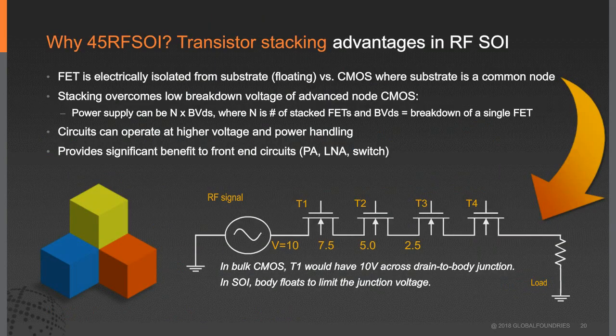Why 45 RF SOI? This is the SOI technology where the FET is electrically isolated from the substrate. So it's floating, versus CMOS where the substrate is common mode. The biggest benefit you get out of this SOI technology is stacking, which enables you to have higher breakdown voltages.